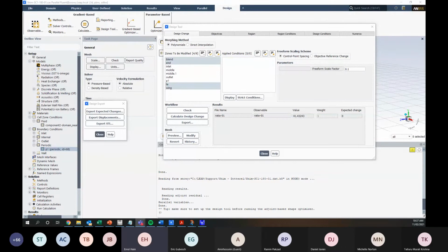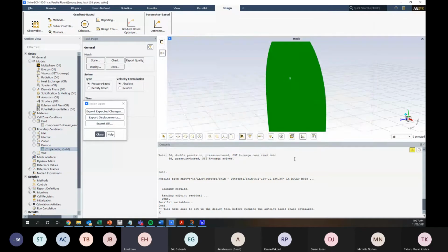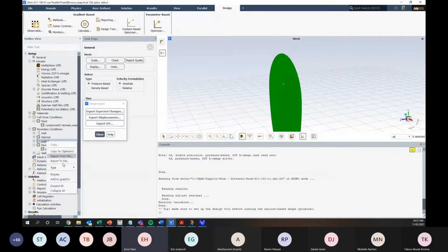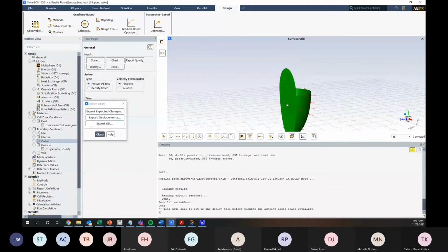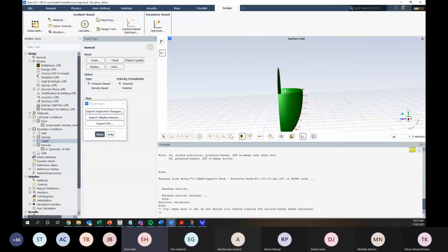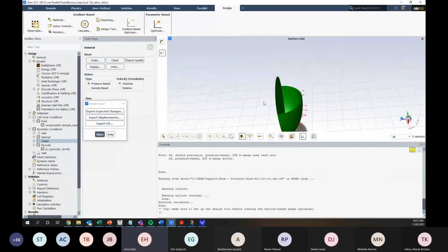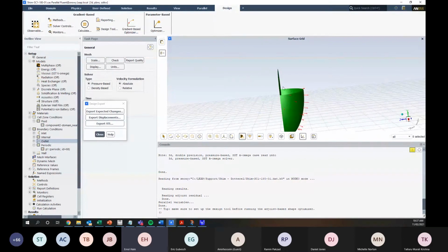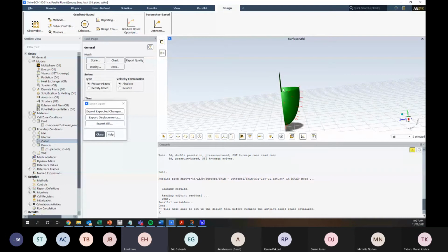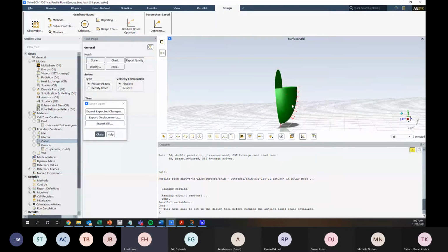Reversed flow on an outlet boundary. So if you think about it, we'll put the outlet here. There's flow coming down, but there's also going to be a wake region around this propeller. So the flow is not necessarily going to be some laminar downward motion of flow. There will be some chaotic nature to it, and that will mean that there'll be places where the flow will want to go out, and places where the flow will want to come in. So that's what your outflow is.